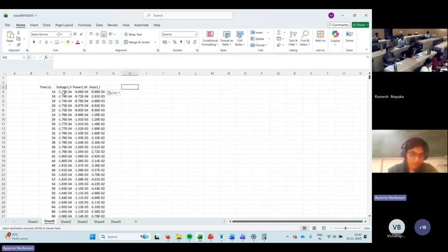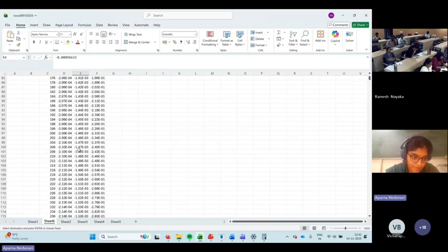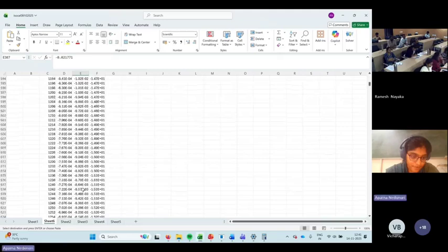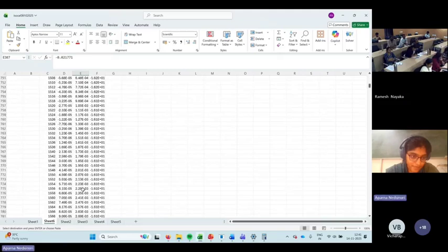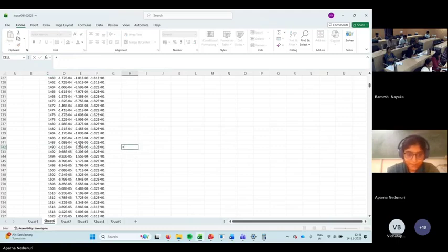Now, if you see, till a certain time you have disturbance in your isothermal calorimeter, and you have negative values for your power. We need to eliminate that data till where the negative values for the power are there. Now you can consider data from this time duration, say from 1490, where you have a power value of this much. Now this power is in terms of watts, right?